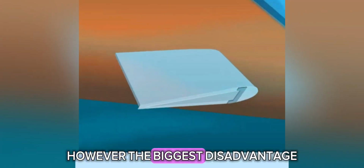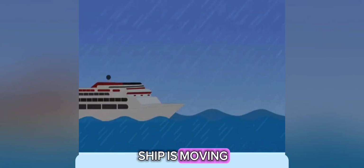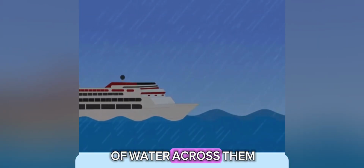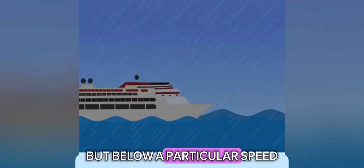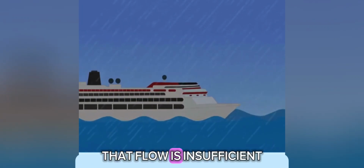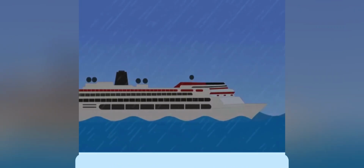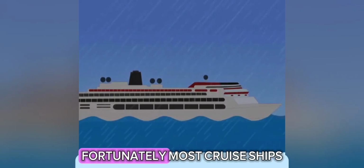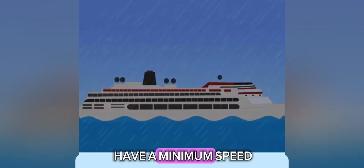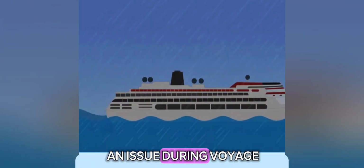However, the biggest disadvantage of these fins is that they will only work if the ship is moving. They require a flow of water across them, but below a particular speed, typically around 6 knots, that flow is insufficient to create a significant righting force. Fortunately, most cruise ships have a minimum speed that is considerably beyond this, so it is not an issue during voyage.